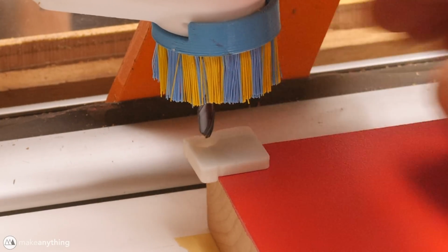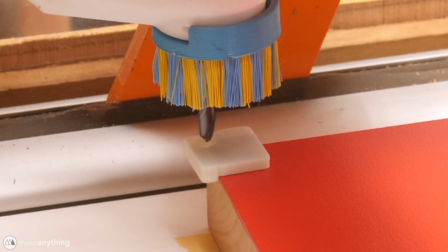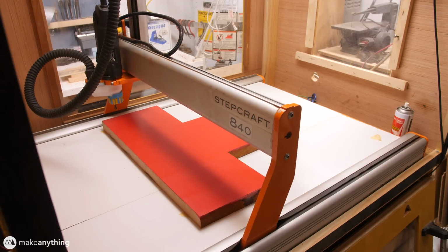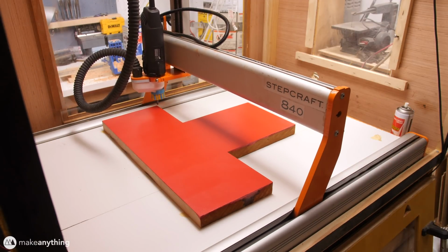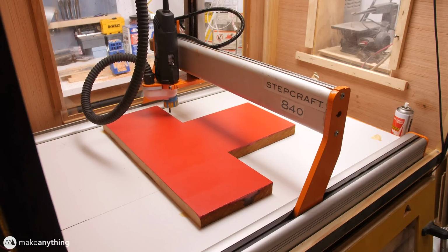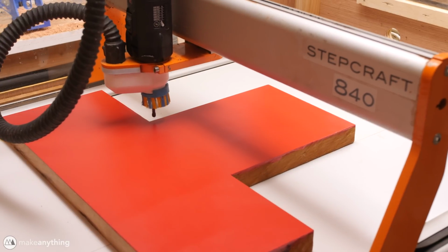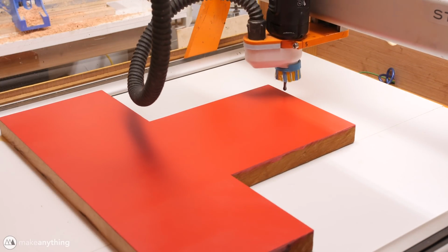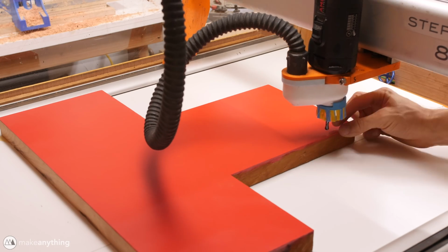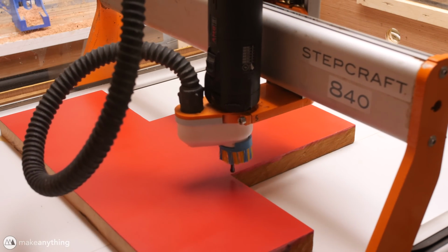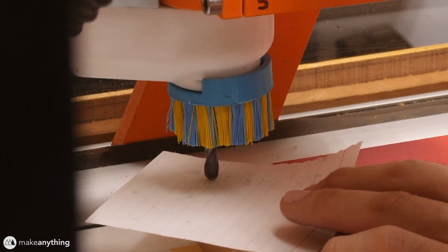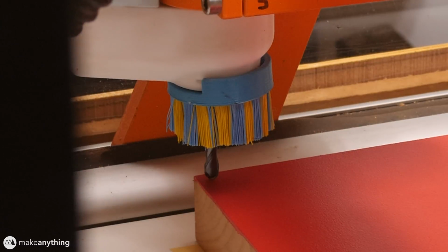And once that's all glued down and fastened, I'll go ahead and zero my CNC to the corner of this stock. I printed this little guide to help me zero the bit right to the corner. And then before doing any actual cutting, I did one last measure of running this process, which basically just moves along the outline of the cut so that I can make sure that my piece is positioned fine and I won't just be cutting in thin air later on. Looks like I positioned it really well, so there's nothing left to do but zero in that end mill and start the first process.